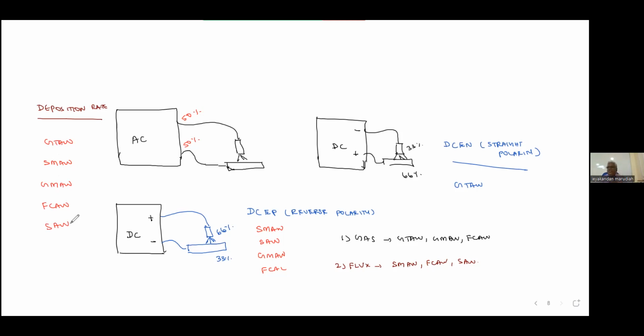Okay. Now finally, the processes can be classified into 4 groups: manual, semi-automatic, mechanized, automatic. Welding involves 2 actions actually: feeding of the electrode and movement of the electrode. If both are by human, manual, for example SMAW. If one is by human and another by machine, semi-automatic, example GMAW, FCAW. Both by machine but under operator control is called mechanized, example submerged arc. Automatic means everything is taken care of by machine, that is robotic welding.